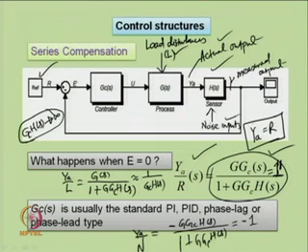That means the actual output of the system becomes the desired output or the reference input. Now, look at the impact of load disturbance on the measured output. Since G C H S is a large number, y A upon L tends to 0. That means the effects of load disturbances can be neglected, can be nullified, can be overcome with the use of large gain of the controllers.